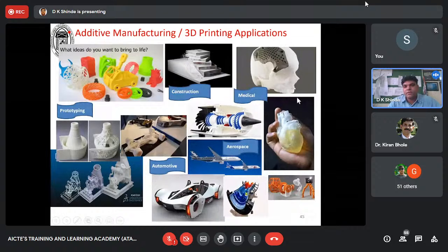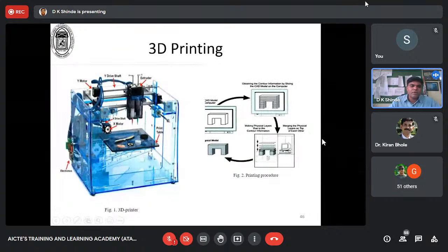components. So this is what we see, a few of those, a heart has been printed using those kind of polymer materials. There are many over there. So this is how it looks. If you see over here, first you generate the CAD model. So this is a frame with X, Y, and Z coordinate system, G code and M code you give, and you generate the code, and that is how we feed the code to this particular processor, and the processor controls the movement of your extruder in X, Y, and Z direction.